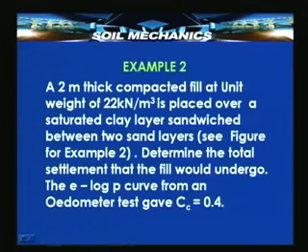But on the other hand, if we put a building on that and if the settlements are excessive, the building cannot adjust itself to these excessive settlements, whereas this fill layer can adjust itself, and therefore, we shall compute the settlement due to this fill layer, and we shall not bother at this stage as to whether it is excessive or within limits and how to contain it within limits. Let us just go over the mere process of computing the settlement.